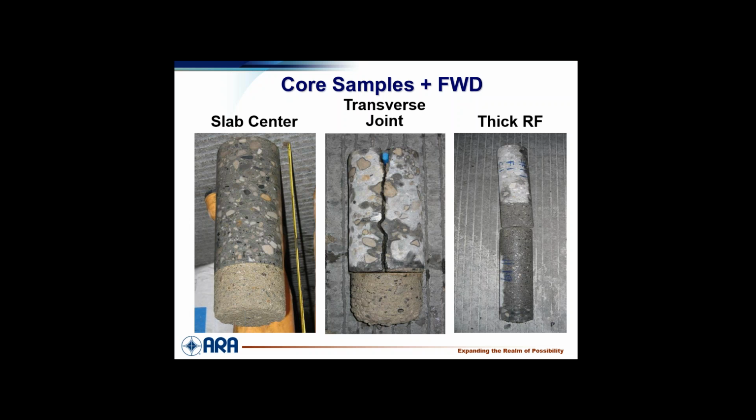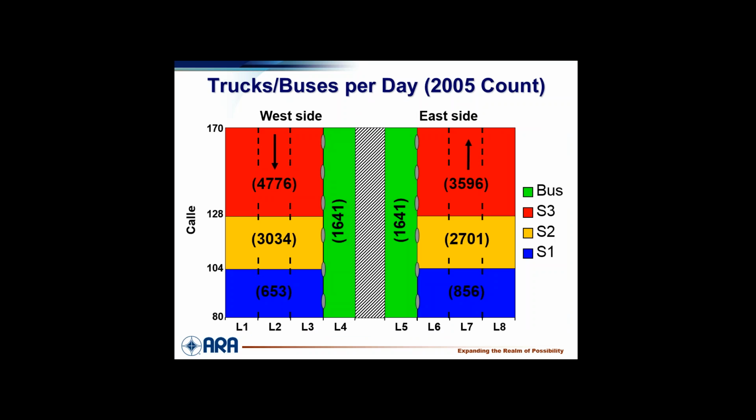Here's a pretty thick one. So you can see how ridiculous this was, trying to even up the old pavement to put the paving down. They didn't think about how durable this was. If they would have filled it with hot mix asphalt, I don't think we would see hardly any of these cracks today. But that's a little more money. You're going to be faced with that in your career all the time.